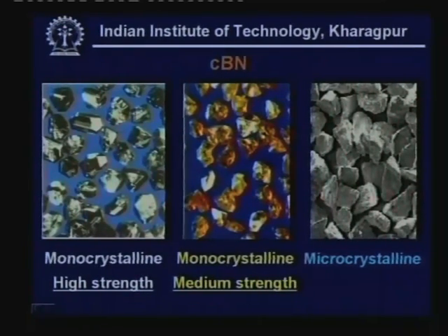What is this microcrystalline grit? These are tiny crystals which are bonded together with sufficient adhesion. Now, during the course of grinding, one particular tiny crystal actually participates in grinding, and it can wear out and some wear flat may develop. This wear flat will increase the force and then that microcrystallite will simply fall off. Then the crystallite just behind it will participate in the grinding action. So, it is a continuous process, but what is the gain? The gain is that this crystal can maintain an auto sharpening character throughout its service life. So, it is a microcrystalline grit having that auto sharpening character.